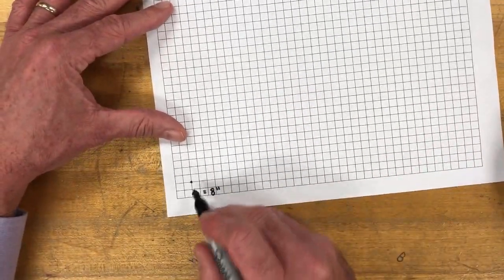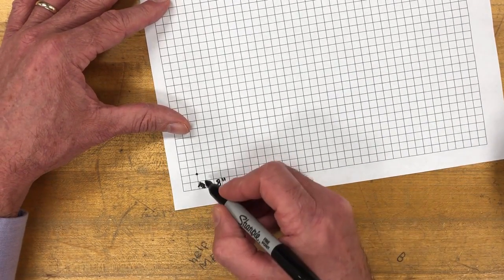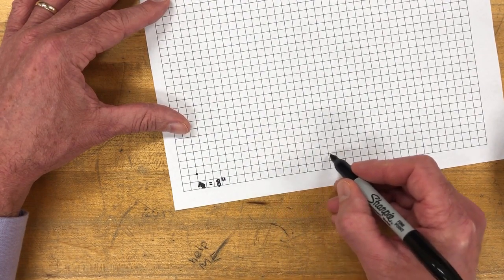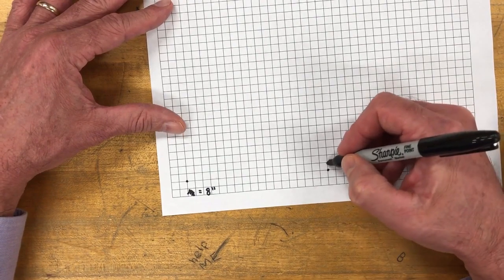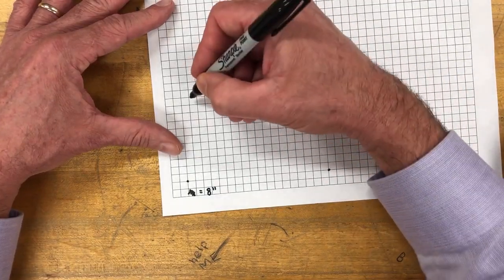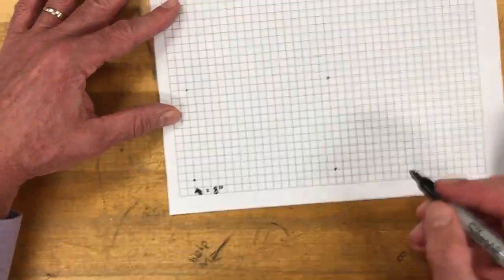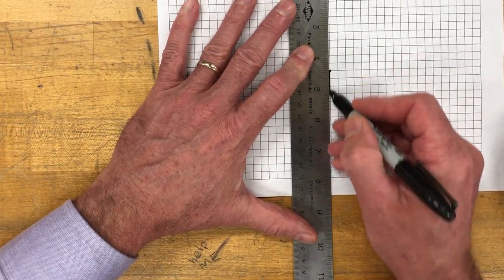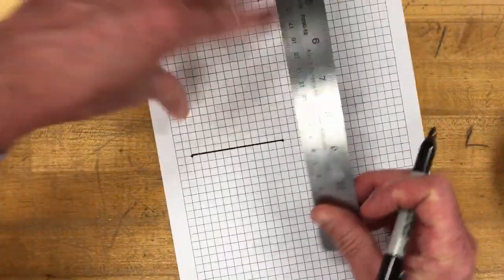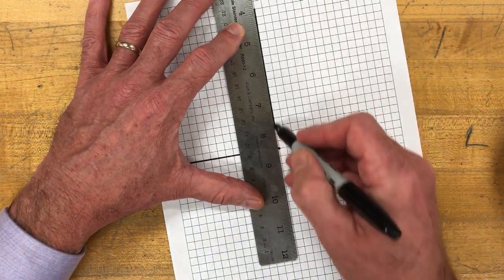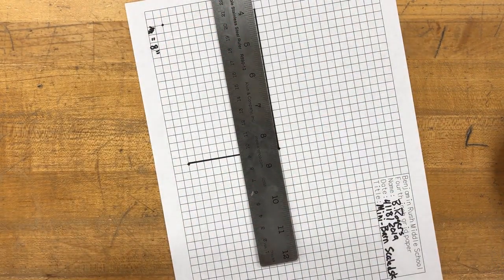So starting down here, you can see we've got the starting point. I'm going to count 18 blocks to the right. All right, 12 blocks tall. I'm projecting over this other side here, something like that. All right, so straight edge. I'm going to draw some lines connecting this up. It's going to be a rectangle in the front view, and we always start with the front view, and then we project our other views from it.